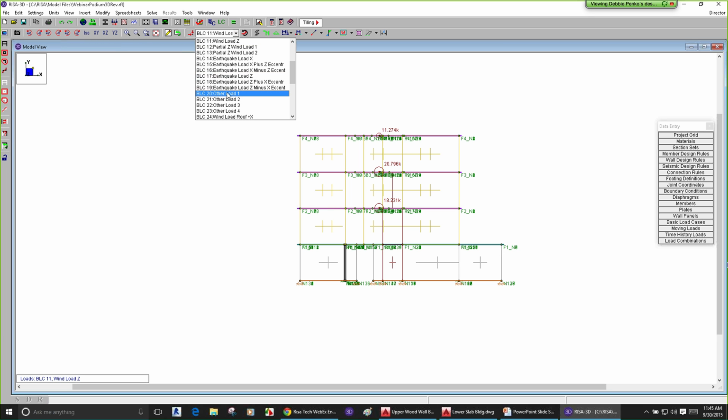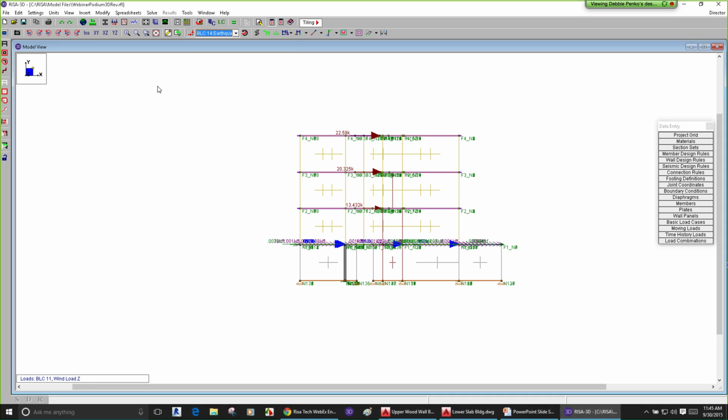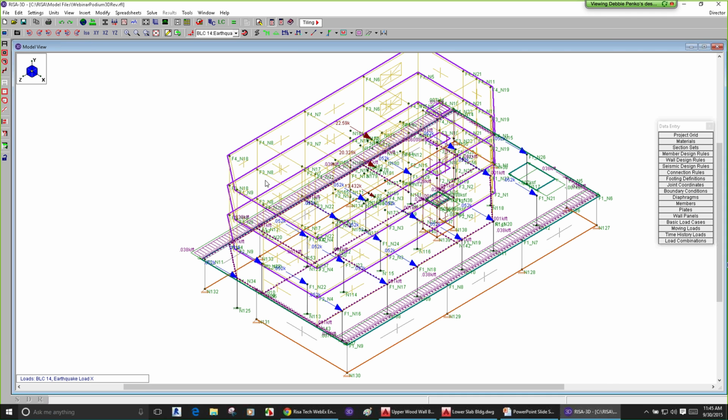We also do the same thing for the earthquake X direction. You'll see that a portion of the load goes directly into the diaphragm for the upper rigid diaphragms, and for the semi-rigid, it goes right into the slab, or what we then break into plate elements, and we'll be distributing it based on its stiffness. So we see all this for each one of our loads.